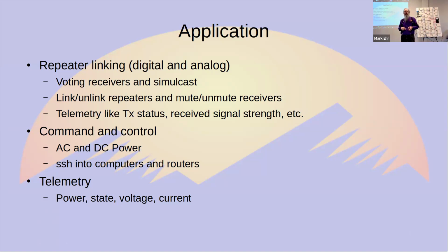If you buy the US version, you can only use the frequencies that are in the ISM band in the US, and you can, of course, buy it for other countries as well. If you buy the international version, there's a way that you can go in the standard configuration without having to screw with the firmware to actually set those in the ham band, which is what we do in most locations.